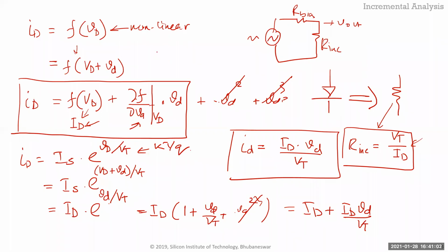So yeah, the question is, see, the diode, I made an equivalent of it as the small signal model, which is a resistor. Exactly. So it's already a linear element. You don't have to linearize it. So the small signal or incremental model for a resistor is a resistor. Same thing. What is the small signal equivalent of a capacitor? Same capacitor, because it's a linear element, right? So this is only for nonlinear elements, right? If it is a linear element, then it's the same. Okay, so when we do small signal models, we'll see that. Clear so far?